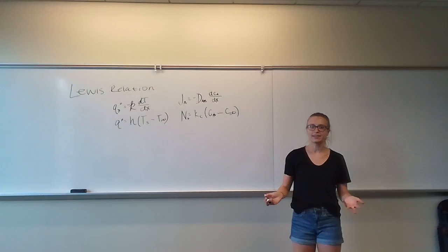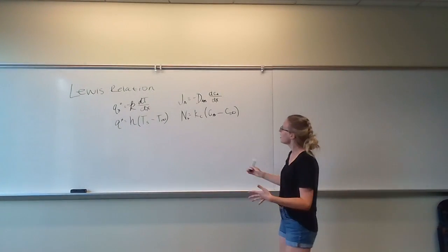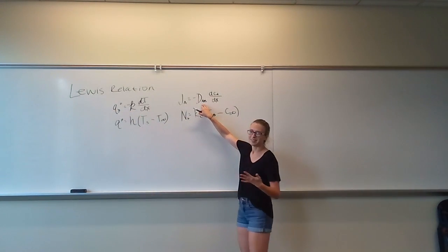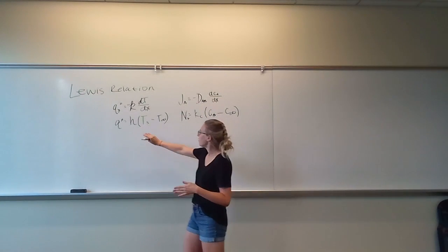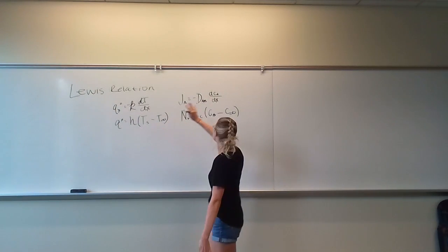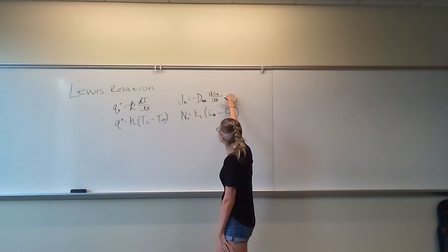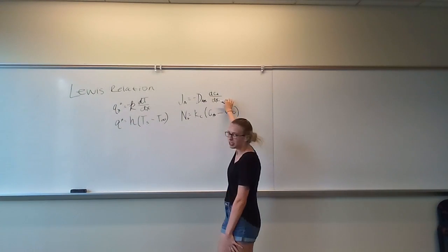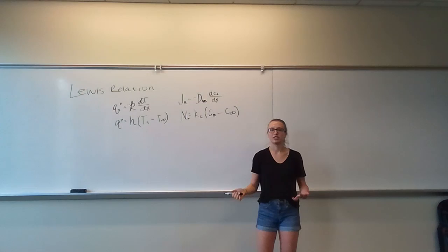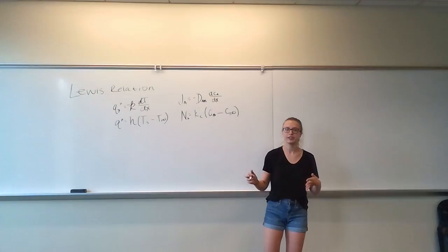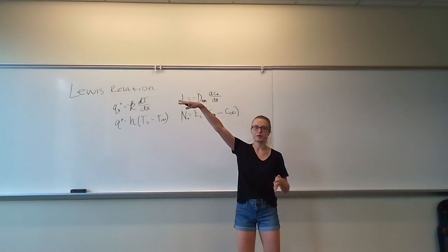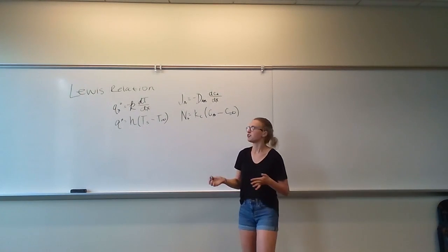So when we're looking at these equations, we can see that they are very analogous. We have some thermal conductivity, and then some mass diffusivity coefficient, and then we have the heat transfer coefficient, mass transfer coefficient, difference in temperature, difference in concentration, and then some molar concentration gradient and some thermal concentration gradient. So these are very similar equations, and they can be related even further by exploring the driving forces of these top two equations in terms of concentration.